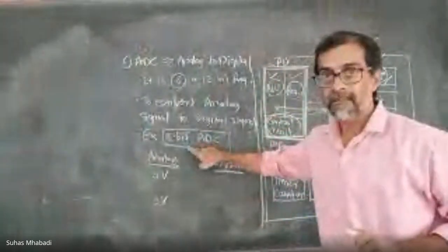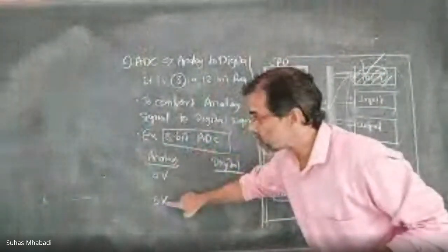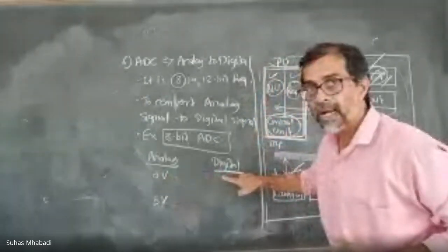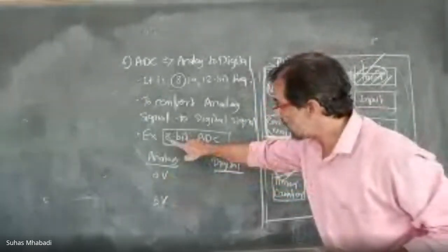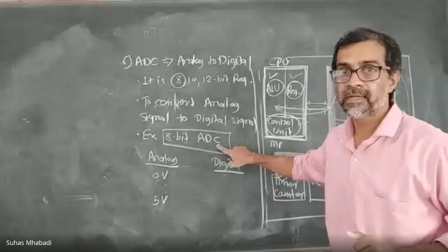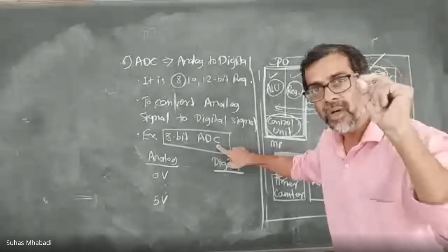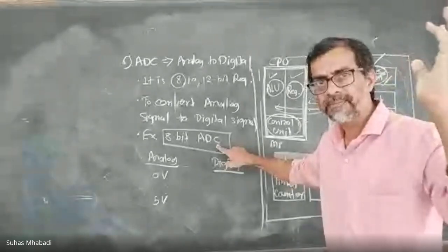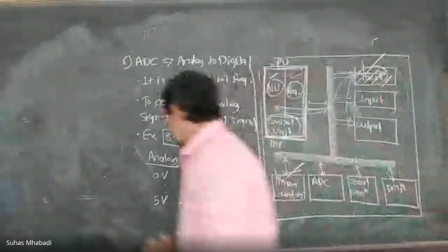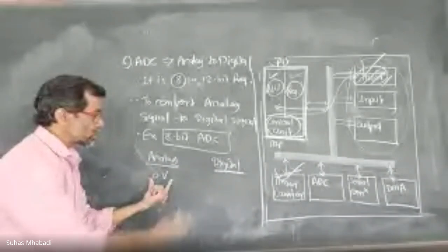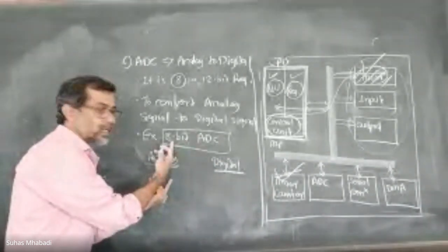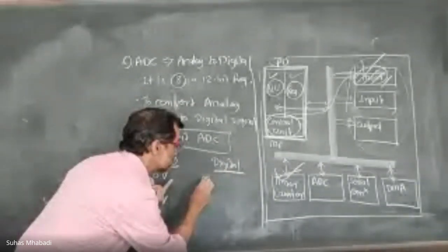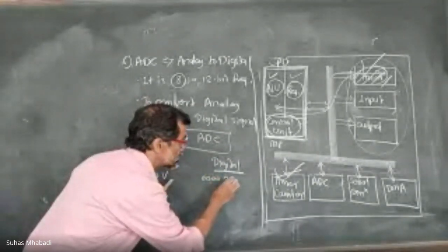What will you get in this register? This 0 to 5 volt range, every stage is converted to a binary format and we get an 8-bit result for every number: 0, 1, 2, 3, 4, 5 or even 0.1, 0.2, 0.3, depending. Example-wise, if the volt is 0, the result available in this ADC will be 8 zeros.